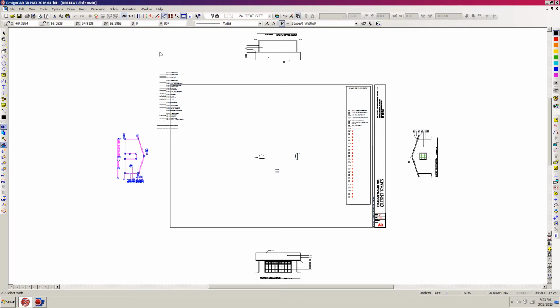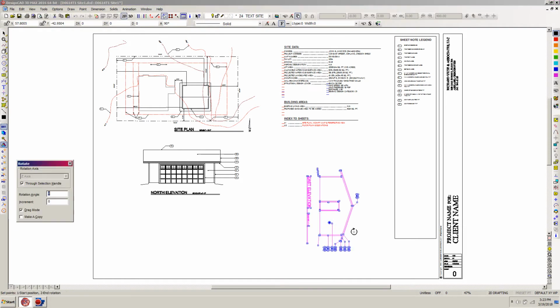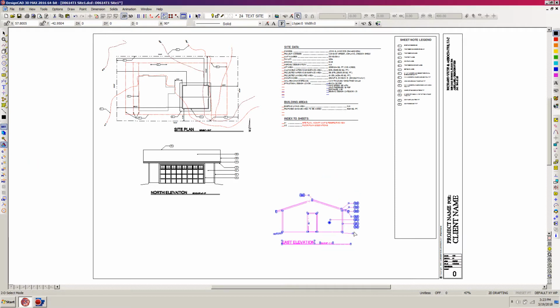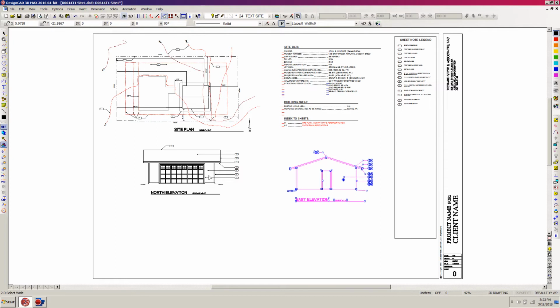Control C to copy to the clipboard. Go to the Windows dialog, go down to the site plan, click on that, and hit Control V and just place it. It's on its edge, but that's okay. We're going to hit R to rotate, R, tab, -90. M for move. Now we might want to align it with this just for fun because it'll look better.